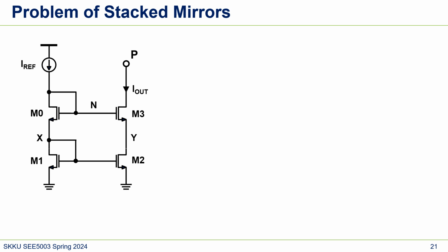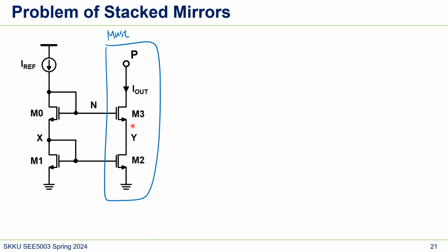Do we even have room for improving the voltage headroom? What I'm saying is, we need this. This is mandatory, because we are going to use this cascode because it has an advantage that protects this voltage of Y from the outside. So the current is matched, aligned better even with channel length modulation. So this is a must. This is our assumption.